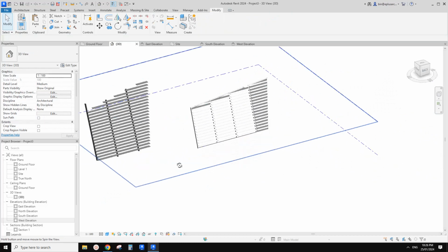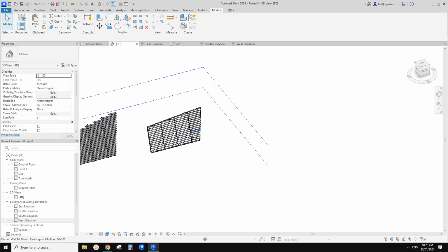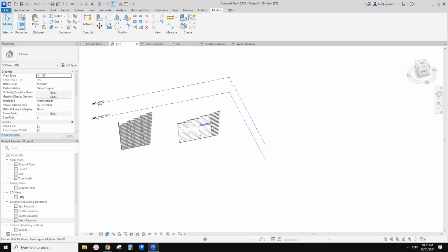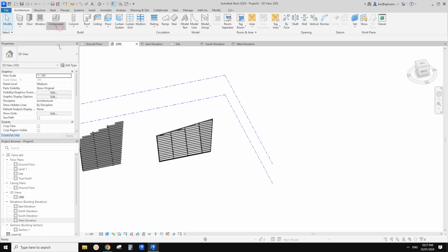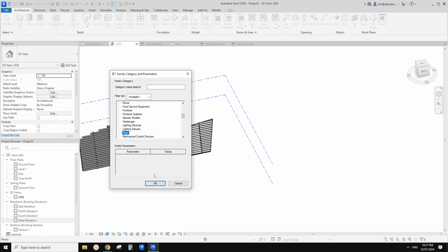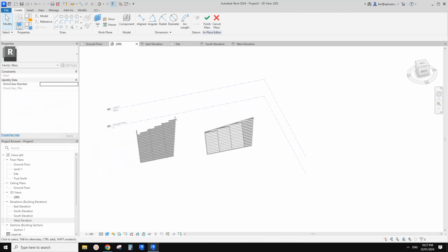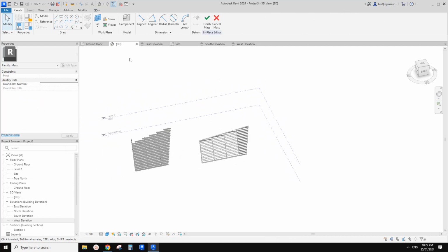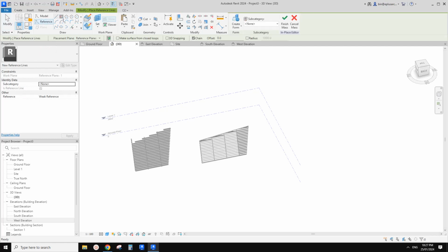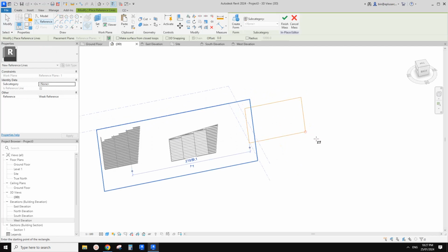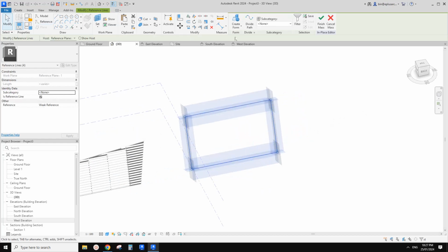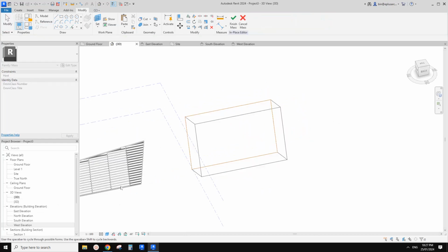Okay, so this is the beam system, and then we can also use an adaptive family. Let's quickly create a model in-place mass. I'm going to use the same reference plane we used for this beam system. Let's set our plane, just use this Reference Plane 1. So reference, and I'll just draw maybe something like this, and then select this, create a form.